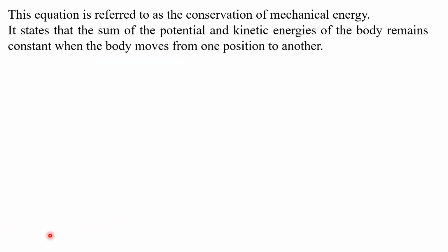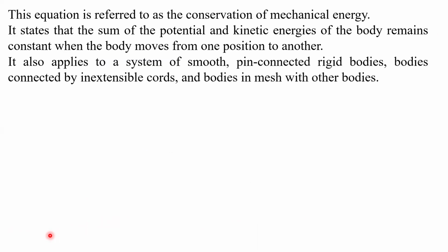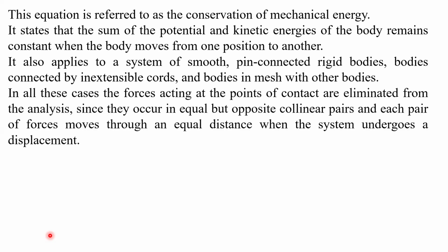This equation is referred to as the conservation of mechanical energy. It states that the sum of the potential energy and kinetic energies of the body remains constant when the body moves from one position to another. It also applies to a system of smooth pin-connected rigid bodies, bodies connected by inextensible cords, and bodies in mesh with other bodies. In all these cases, the forces acting at the point of contact are eliminated from the analysis, since they occur in equal but opposite collinear pairs, and each pair of forces moves through an equal distance when the system undergoes a displacement.